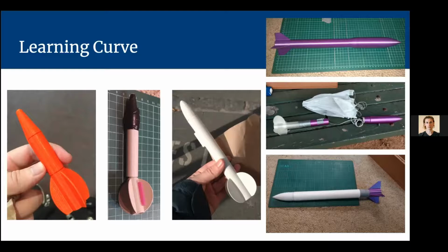And so yeah, from that rocket, I learned that, okay, you need to have proper stability. So in the second rocket from the left, the one with the little pink straw on it, the gray rocket, I basically doubled the area of the fins, which moved the center of pressure back to make it more stable. And you can see on the nose there is actually a wad of duct tape that I wrapped around the nose to weigh the nose down, to move the center of gravity forward.